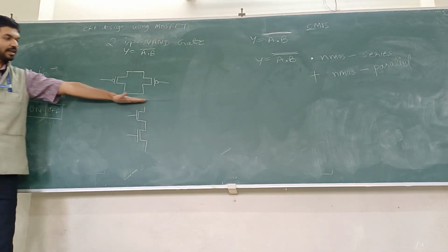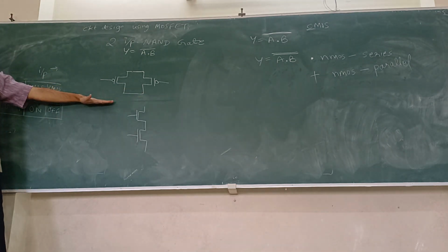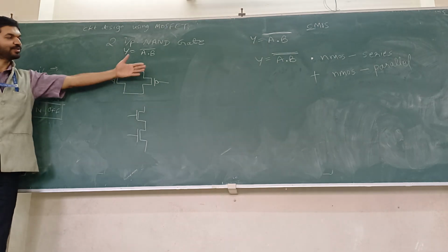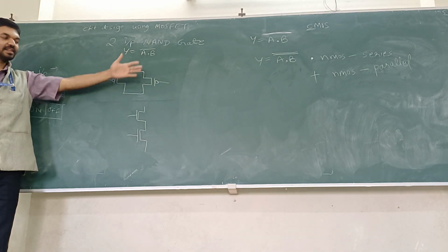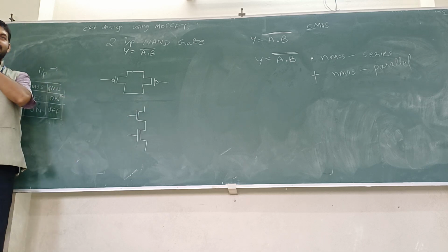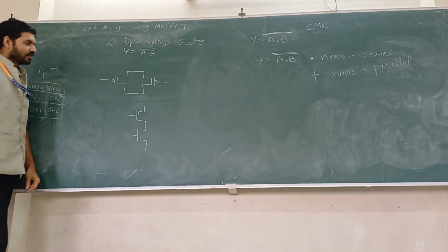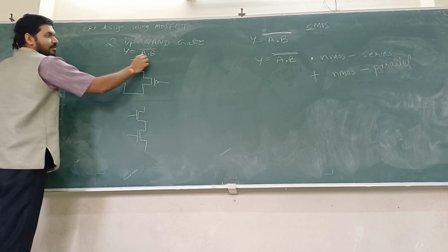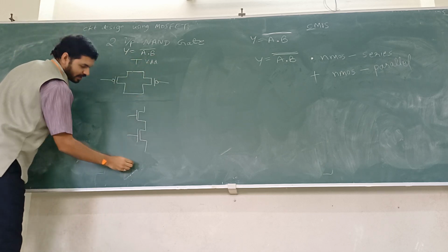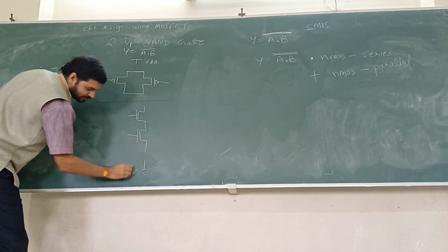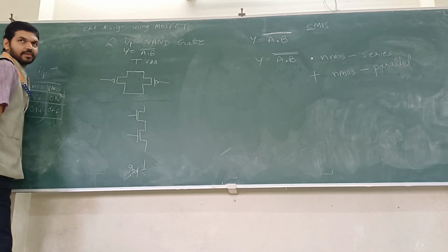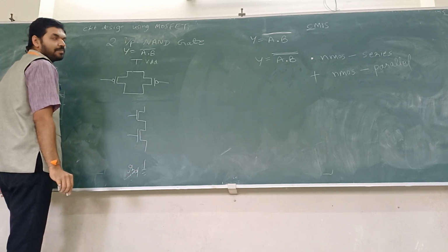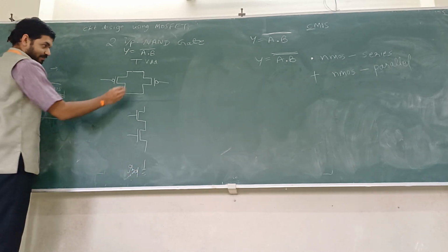And here is my imaginary line. Don't forget that. PMOSFETs above the imaginary line, NMOSFETs below the imaginary line. Okay. Now, as usual, we have VDD at the top and we have ground at the bottom. Fine. Next, you tell me.